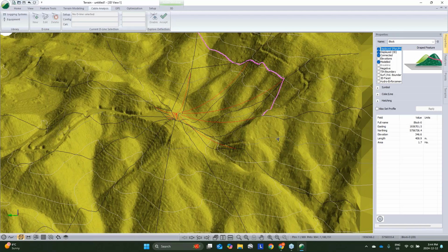So, and then in terms of the path explorer tool, which is that kind of, I want to go from here to there. Well, your point A is wherever you're branching off your existing road. Point B is that landing location that you want to get to, that you've confirmed has good deflection that is worthwhile to try to get to. And then in a matter of a few seconds, you can determine feasibility, put some cost to it, and even kick it ahead to actually using your whole drawings and seeing how much dirt you're moving there.